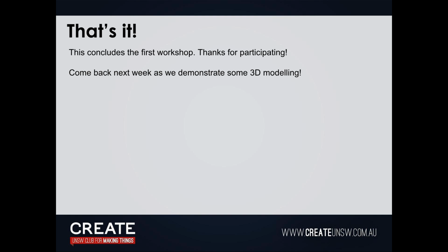Done, right? Now you can extrude that. You can do one side or 2 sides. We'll do 2 sides because we want them both way through. Distance doesn't matter too much. That's good. Now, there we go, you have your pins there for your fingers.